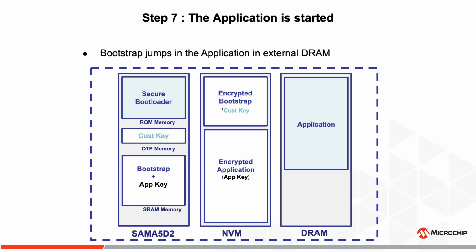In our case, secure provisioning and secure boot are free. They're relatively low touch in both the engineering effort and in the factory. By having encrypted Bootstrap and encrypted applications, you can protect your production line from mishandling and or misuse of the programming tools.